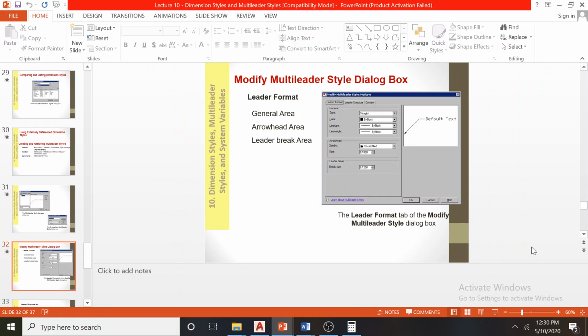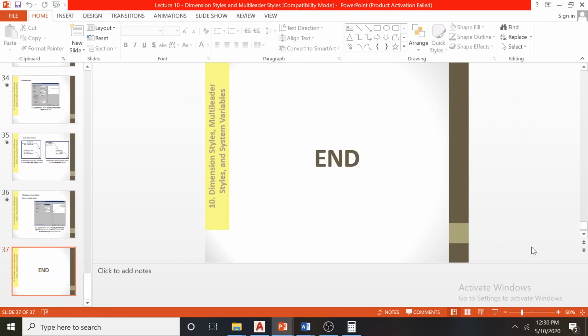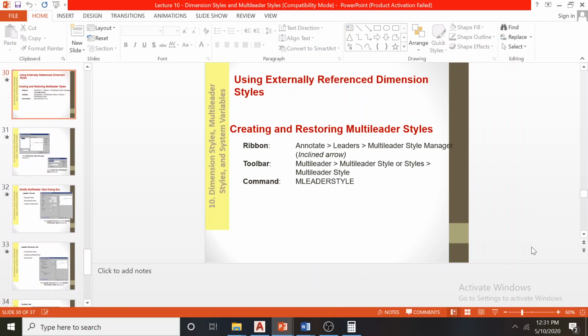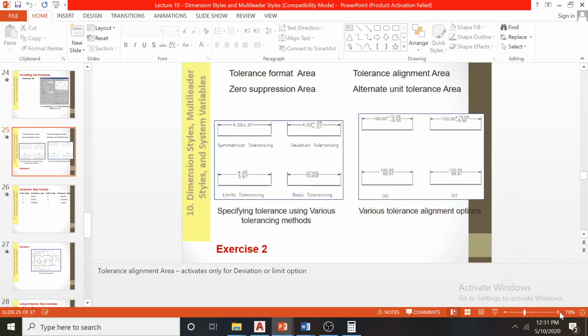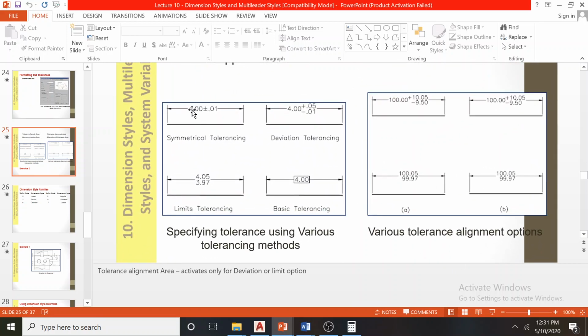We cannot manufacture or construct the drawings' actual work according to the given dimension. Always there is a plus or minus error, and that error is called tolerance. This is the actual value you expect, but your lathe man or the masons cannot do it accurately, so you have to give a small tolerance. This tolerance value may be important in critical designs like mobile phones, but in masonry work it may not be really critical. So depending on the field you use this drawing in, you have to decide the tolerance value.